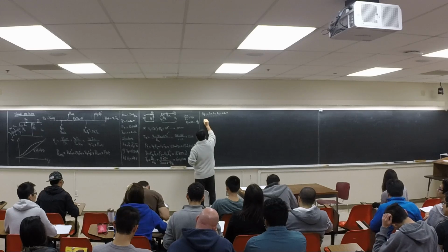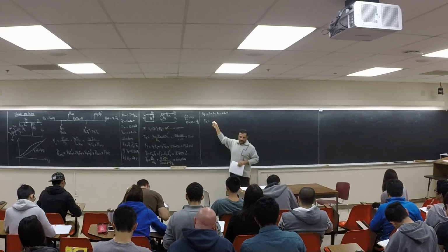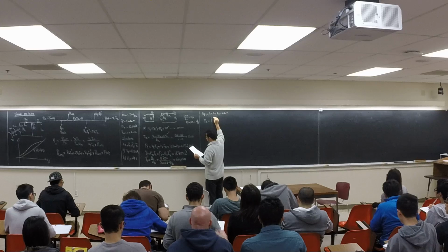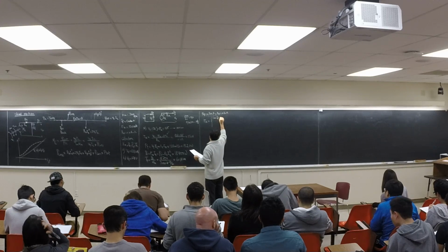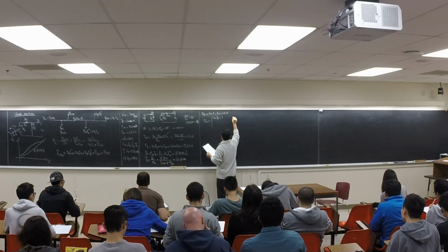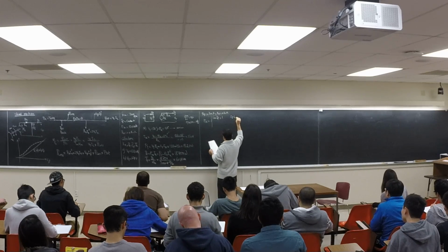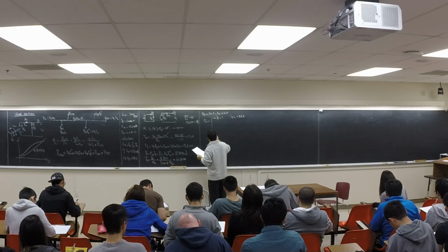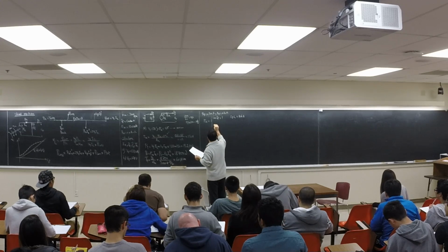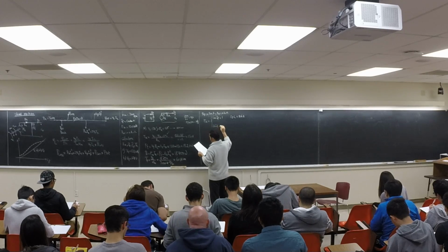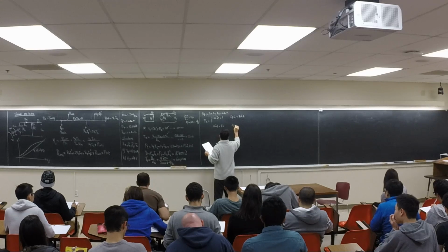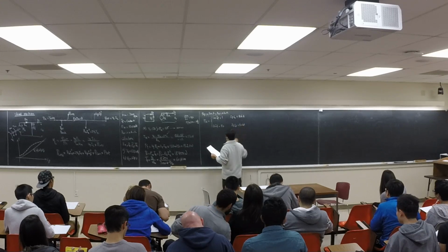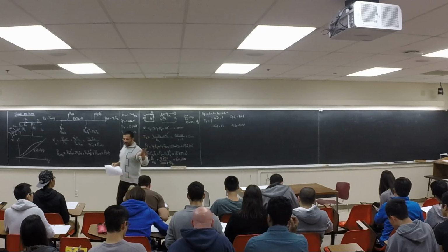It says this machine has this no load characteristic: EA is equal to 100 IF plus 1 if IF is less than 0.806 amp, and is equal to 2IF plus 40 if IF is more than 0.806. So this is the no load characteristic of this machine.